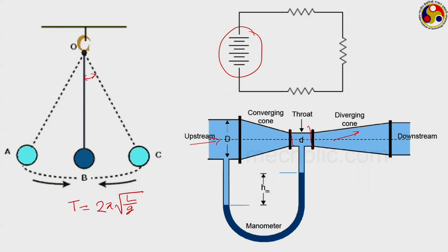And using some kind of manometer or some other device, we measure the pressure difference between this inlet portion, that is before entering your venturimeter, and this throat section, and that measurement generally gives us a measure of the total flow rate, which can be written as, if m dot refers to the mass flow rate, we can write this as A into CD into power 2 P1 upon RT1 delta P whole to the power half.